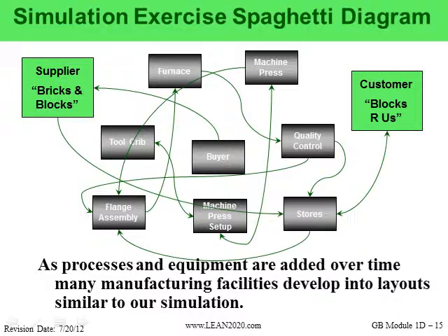So in this particular case, what I'd like you to do is take a look at your facility, and if there's a floor layout, do a little spaghetti diagram. Trace out where the product goes from one department to another, and see if there are some opportunities. It may not be an entire facility reorganization, but there may be some opportunities to redesign your facility and improve the flow, reduce transportation, reduce motion within your work environment.